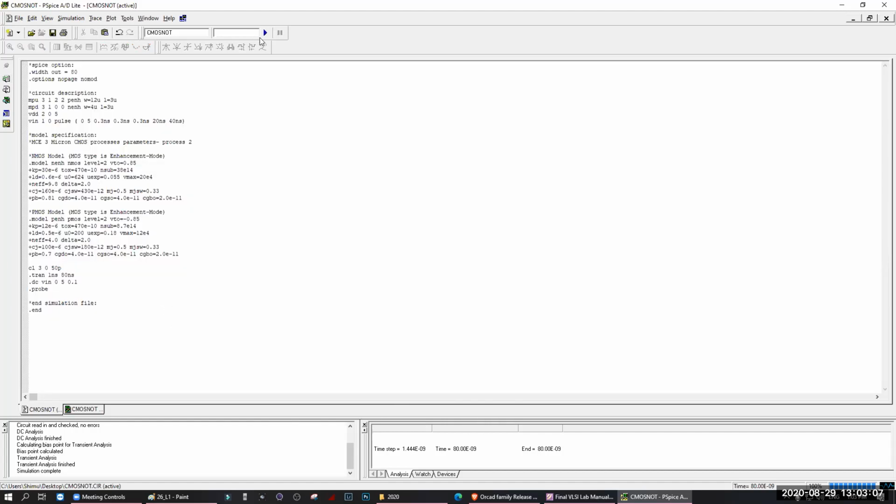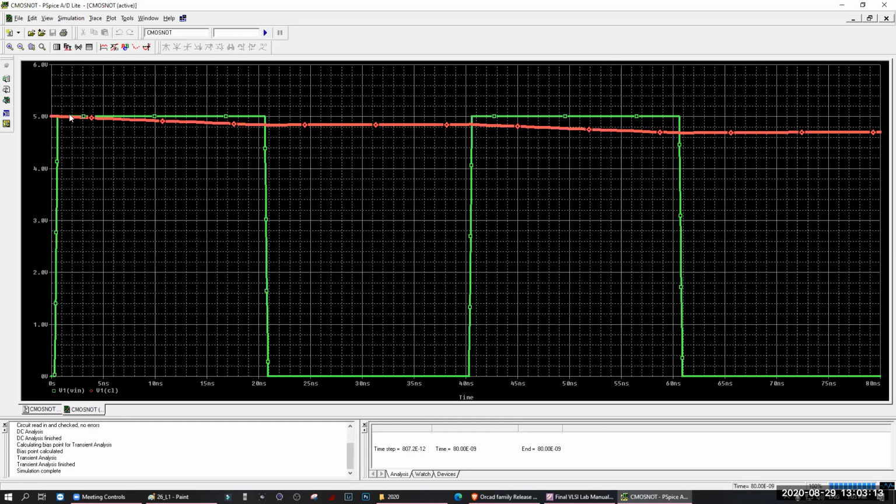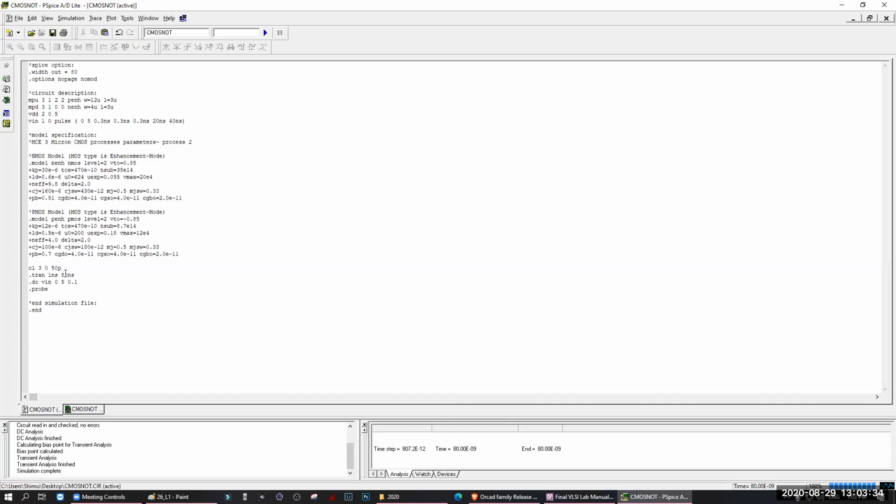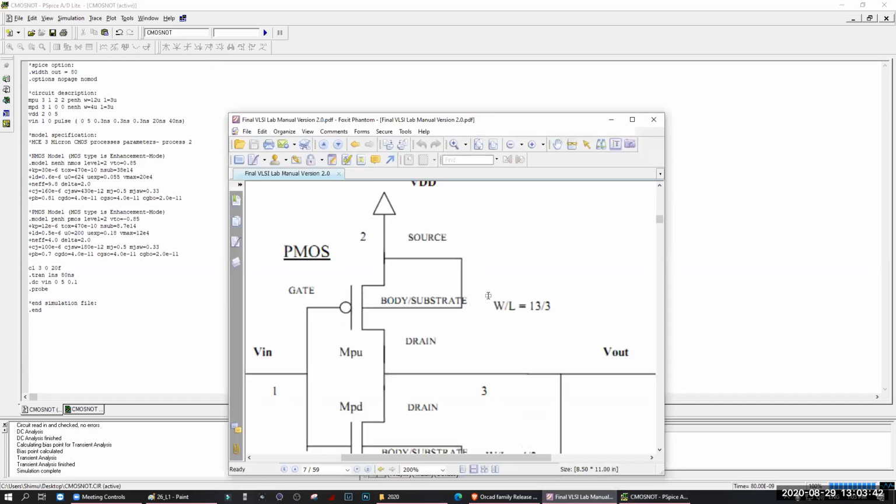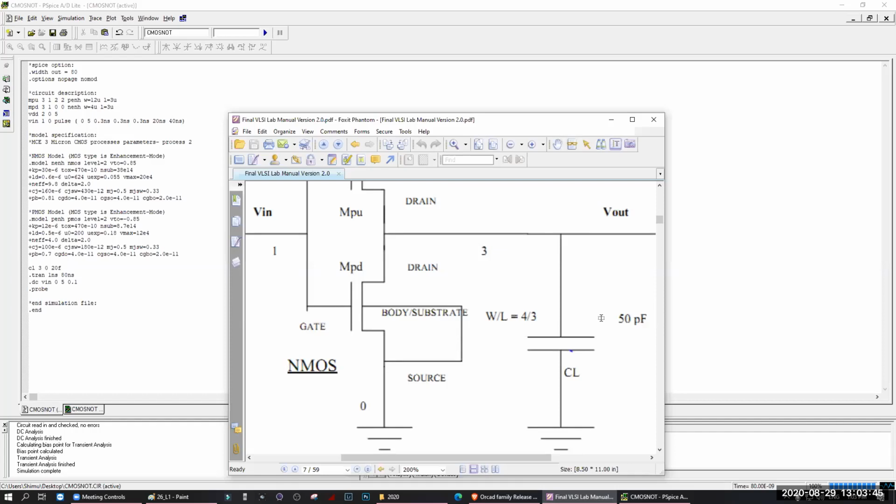Let's use picofarad. Can you see that? It is discharging. It is slowly discharging, but not fast enough. So it is not fast enough to go down to 0 and go to the high. Understood, my dear? Yes, sir. So what I can do, I can reduce it, let's make it 20 femtofarad. That's why our graph, not our circuit, was picofarad, but our code is femtofarad, right?